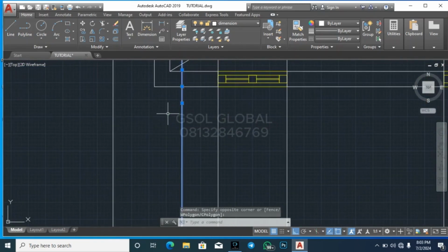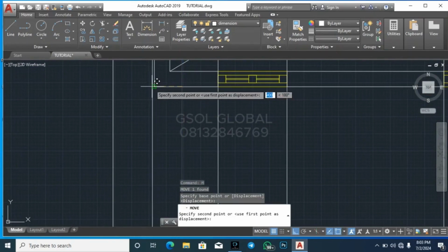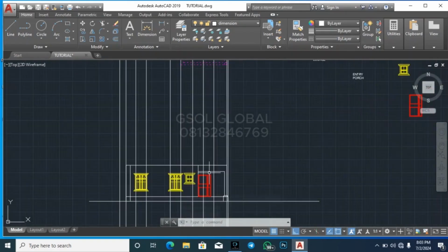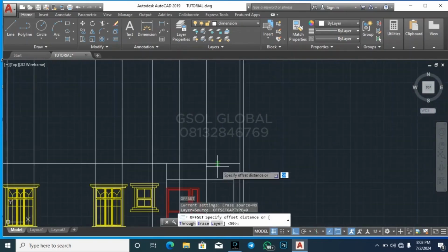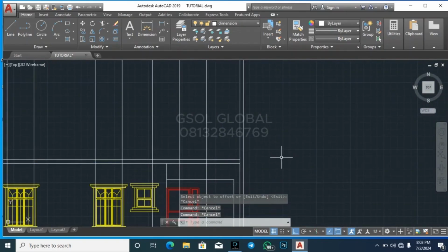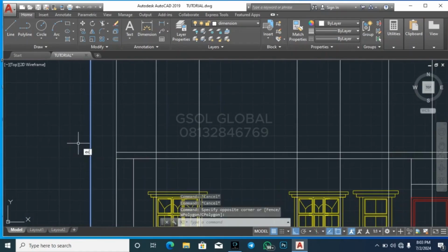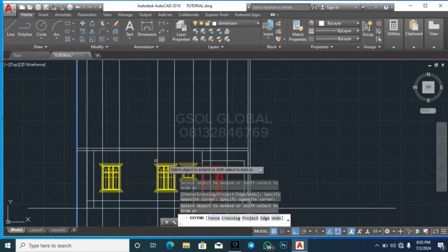So you shift your construction line to this other hand. Good. This is what we are having now. So we can go ahead and start doing what we want to do. So I'll make an offset for the slab, which is 150. Okay. So I'll make an offset for what? The slab, which is what? 150. So I will extend this particular slab boundary line to both ends.